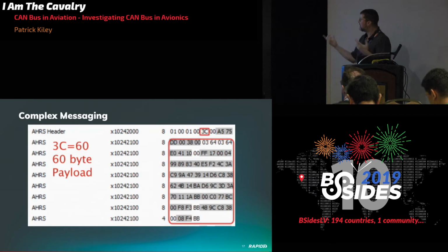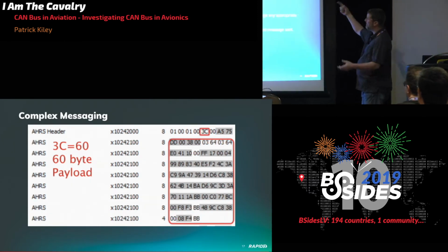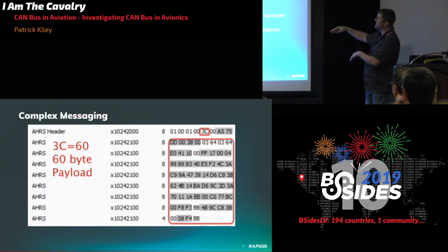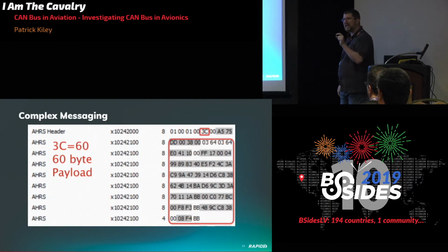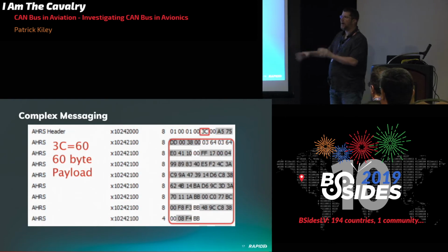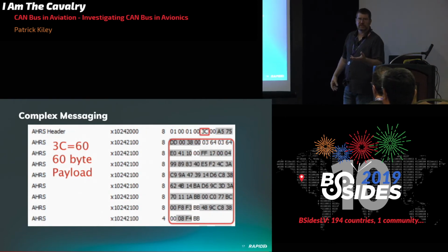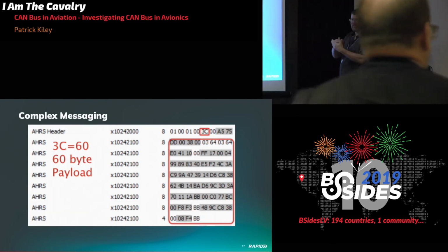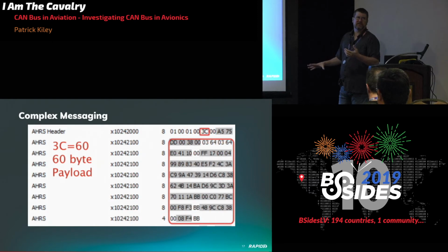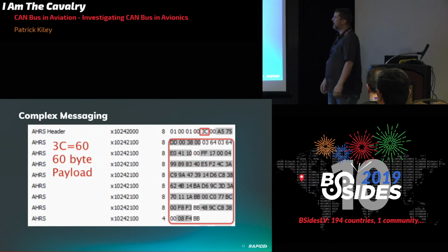And then the way you would actually attack this: you read in the header, you store the message size as a variable, you read the subsequent data frames into an array, and then you replace just the segment of the data that you want and dump it back out on the wire. Because it's a more recent message, it'll be trusted. And you just have to do that more frequently than the existing system, or wait until the legitimate message comes in and immediately send your message afterwards. There's a bit of a timing thing there, but it's definitely a legitimate attack.